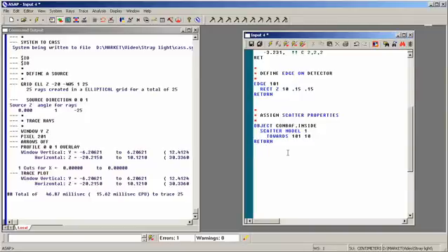Let's put our rays into our system. Define source. Grid elliptic Z, again, it's at Z equal minus 20. That's the entrance to our system. It's a semi-diameter of 6, so we're going from minus 6 to 6 in X, minus 6 to 6 in Y, 1 ray in the X direction, just for simplicity, and 25 in the Y. Source, direction, 0, sine 20, cosine 20. And do our ray trace. We'll do our profile command just as we did before.